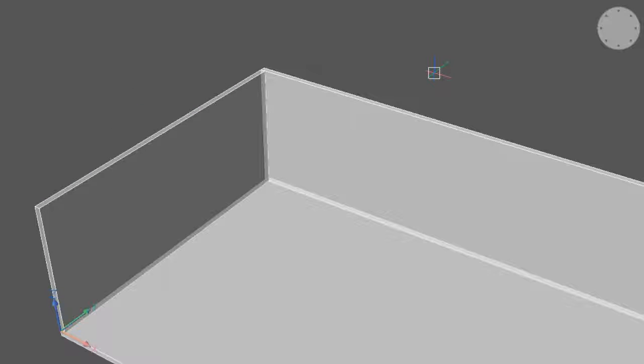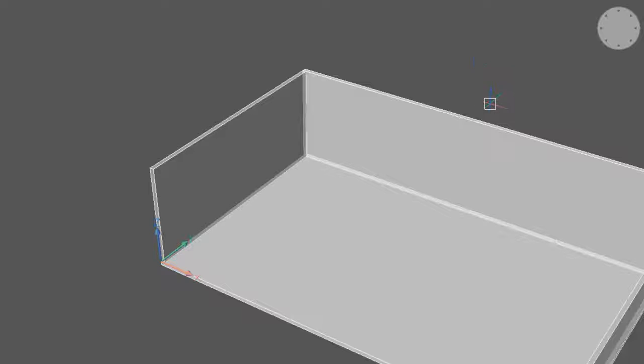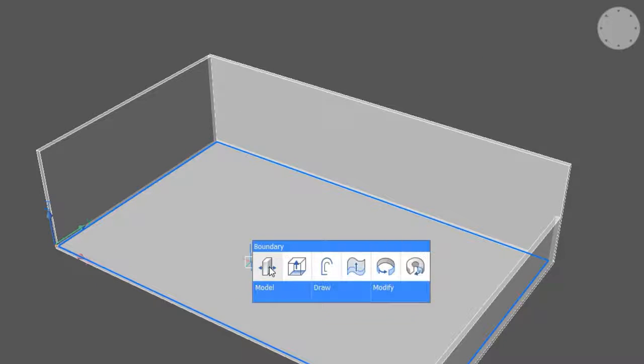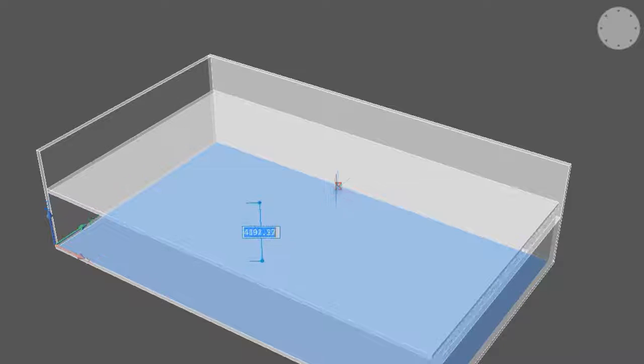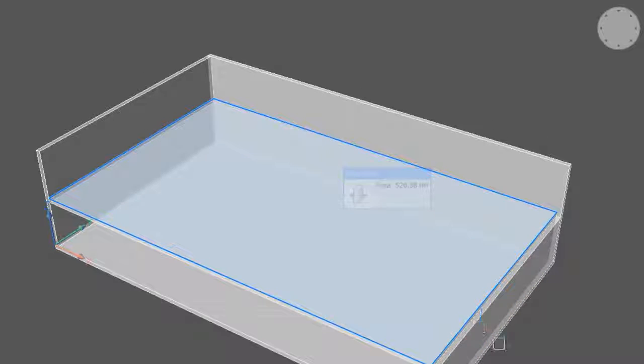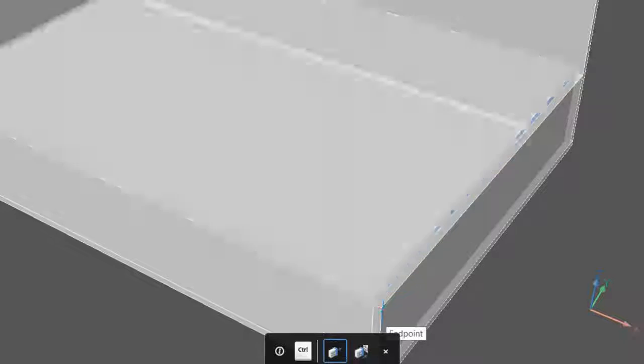Continuing the theme of showing how BIM Drag can be used, we'll highlight the boundary of the floor surface. Select BIM Drag and generate a new floor slab for the level above. Highlighting the end surface, we'll use BIM Drag to extend it over the top of the wall below.